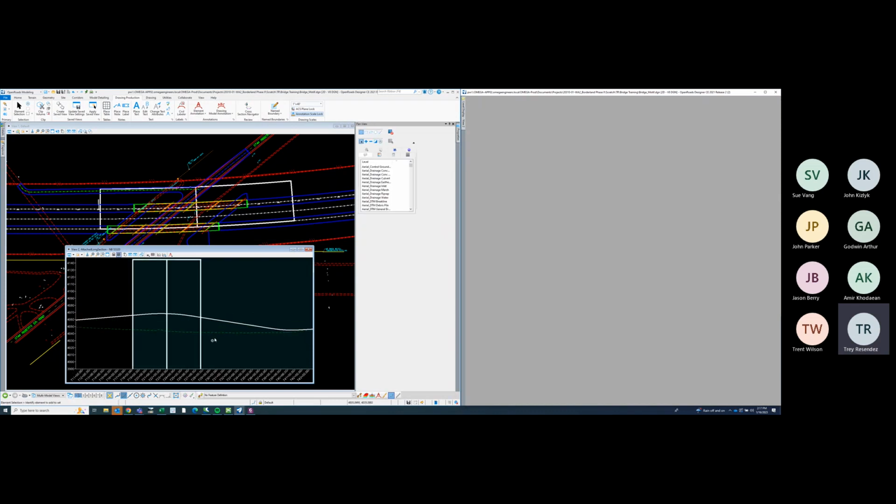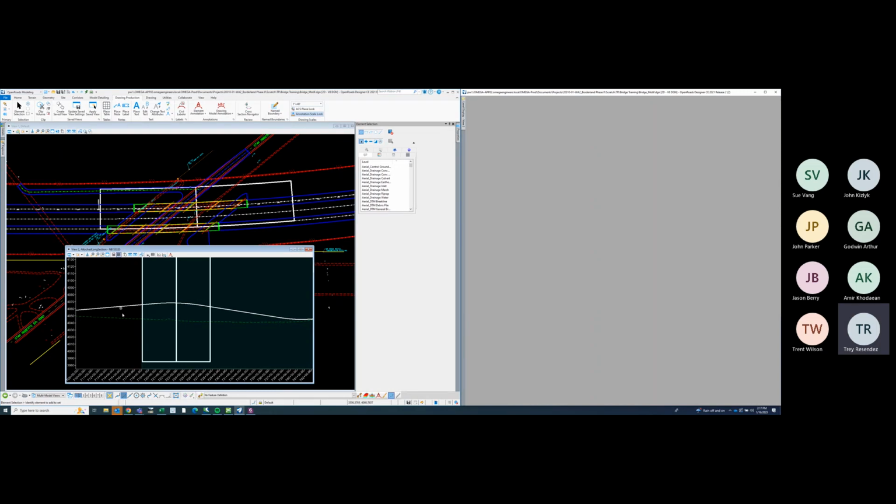This is something that I guess Amir and I figured out while we were working on the Lufkin project, but we figured out that this is going to be the best way to do it. So anything you draw in here, like all your bridge elements, your offsets for the rail or your abutments, your columns or whatever, draw them here, and then they're going to show up when we cut our sheets here in a second. So just to show you that it works.